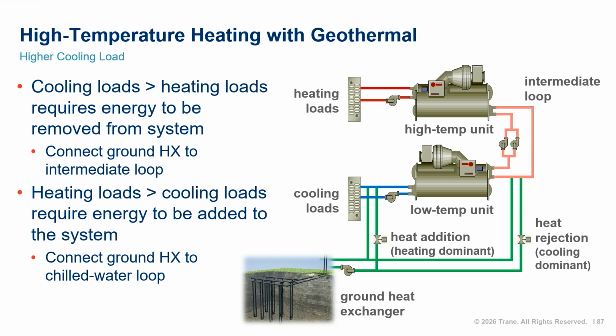Many existing heating systems are designed for high temperature heating hot water, often in the 180 degree range, and in many cases, those systems must remain in place while heating plants will come and go. So cascading units to achieve the required lift is one way to do this.